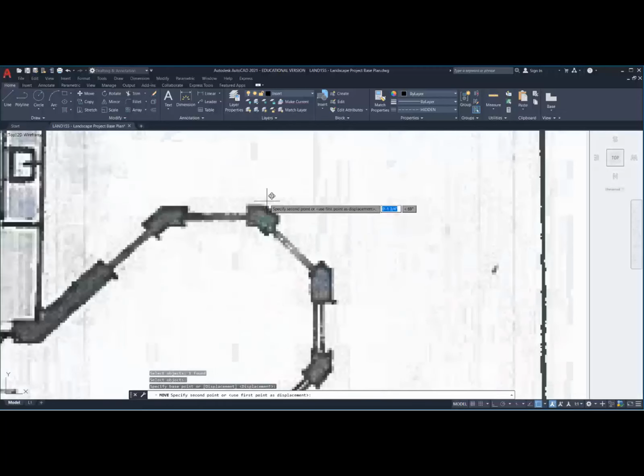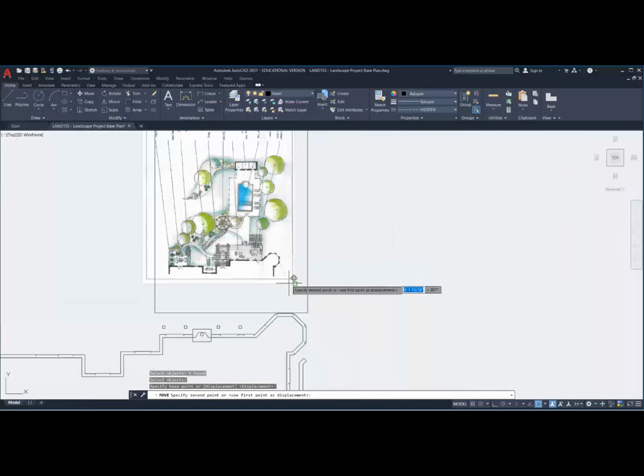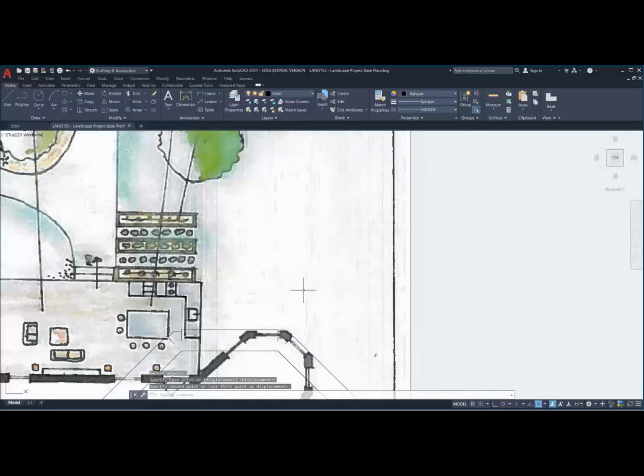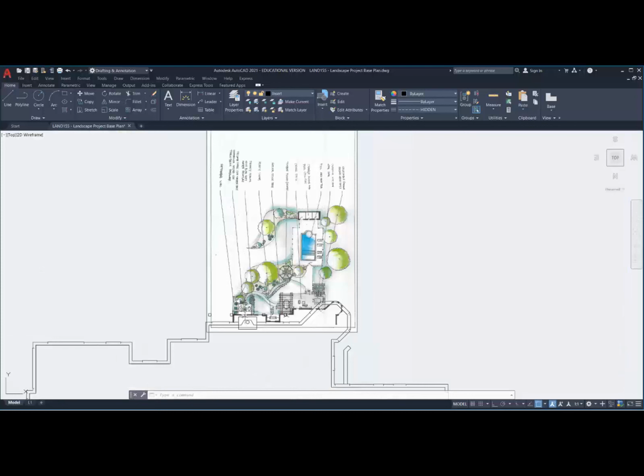So from there, I'm going to move that particular image right to the corner of the house, which is right here. So those 2 points are lined up, as you can see, but the scale is way off. My image in the background is far smaller than the actual graphic. So now I'm going to scale it up. And when we scale it up, we want to pick the furthest points apart to get the most accurate scaling. And this will make sense as I go through it.